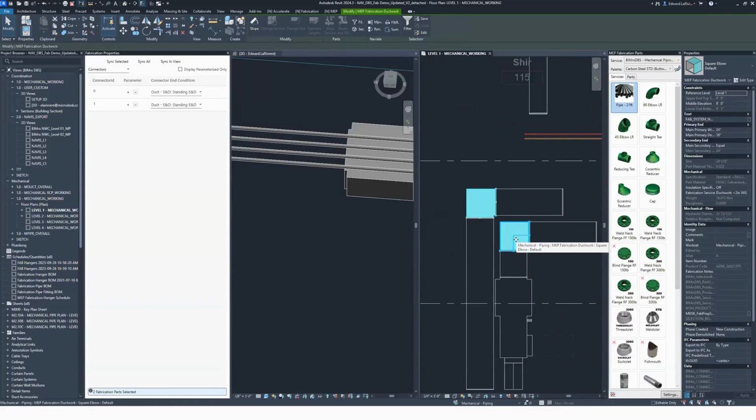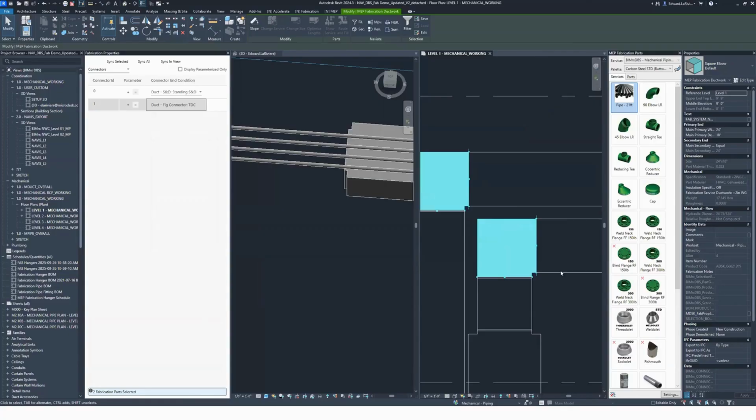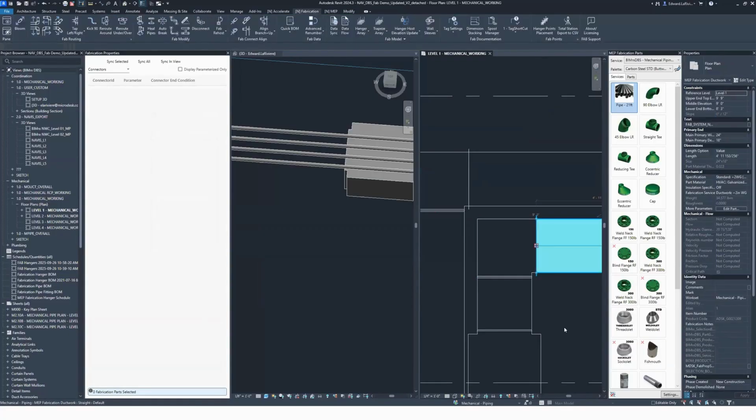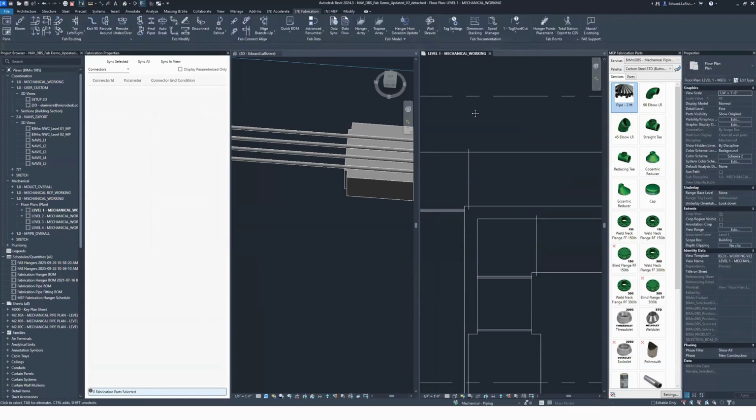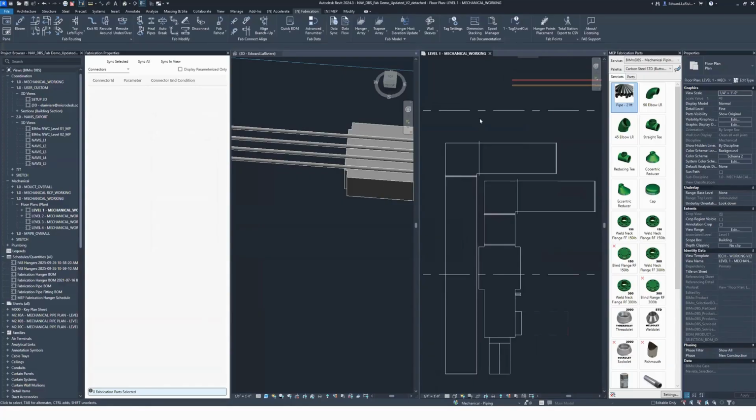You can always hop in here, and if you grab multiple items, where Revit says no, Naviate says yes. So if I want to drop one of these sides to TBC, absolutely can, and we'll see that update happen on both of them. We'll also catch that update did happen to their connected elements as well, so we're good to go. Hopefully you're not making changes like this that often, but if you do get stuck in a snag, we're here to support you.